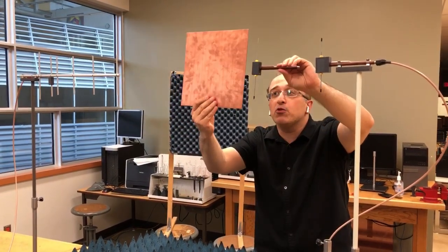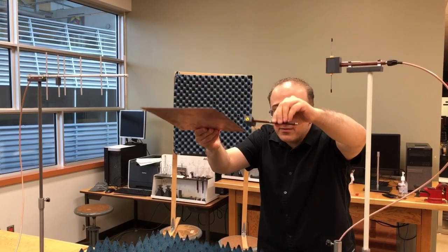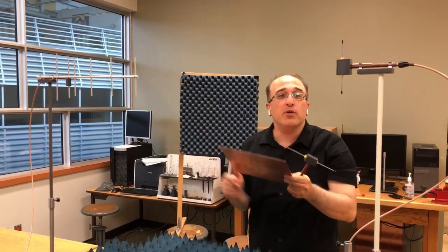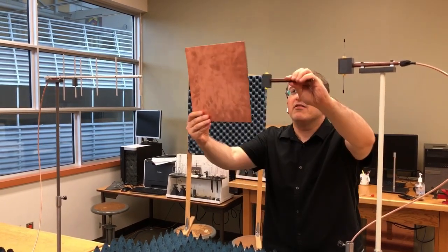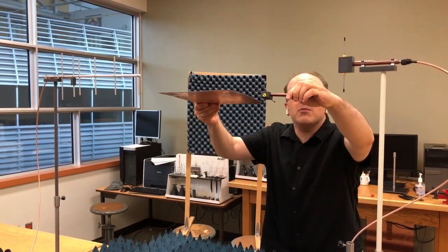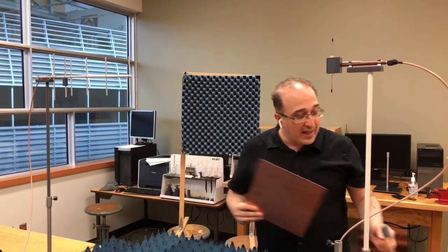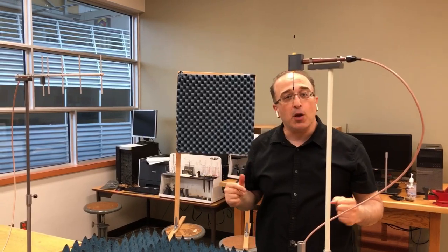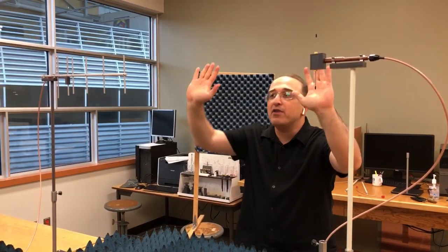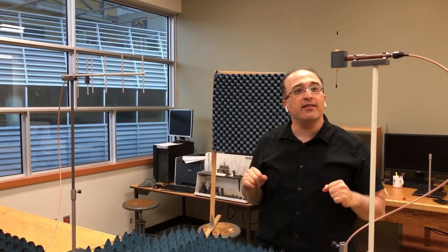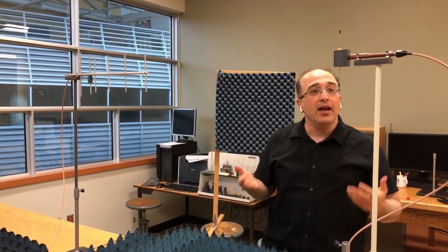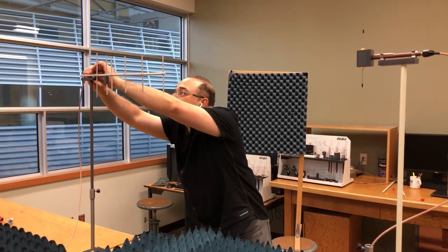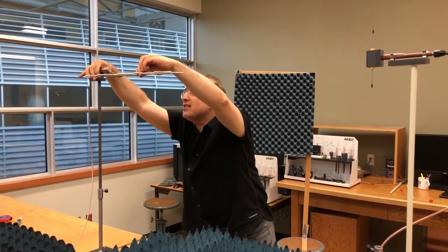But remember, when you rotate everything 90 degrees, you also need to rotate the transmitting antenna 90 degrees to perform the E-plane cut, because otherwise the polarization becomes horizontal. That is right now an H-plane measurement setup. If I want to make it E-plane, everything should rotate 90 degrees, and I'm going to use the same measurement system. So I'm going to loosen this up a little bit, and I'm going to rotate this 90 degrees.